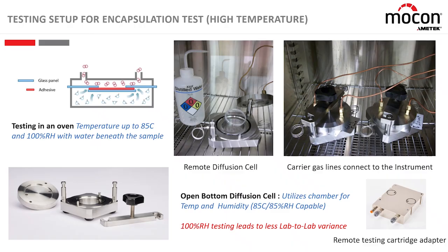I do get asked still like 85C, 85% RH. In our laboratory, we only test with 100% RH. We don't have an 85 chamber. And anecdotally, I've been told by customers that have them that they love them because they read the readout of them, it says 85. I love my testing. Until they get their second one. It's very, very difficult to calibrate 85% RH at 85C.